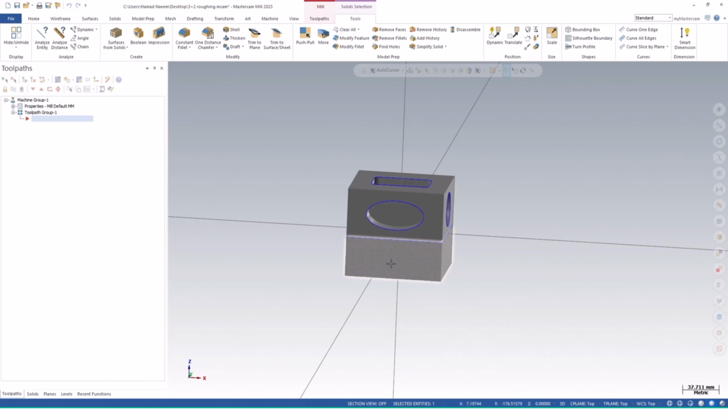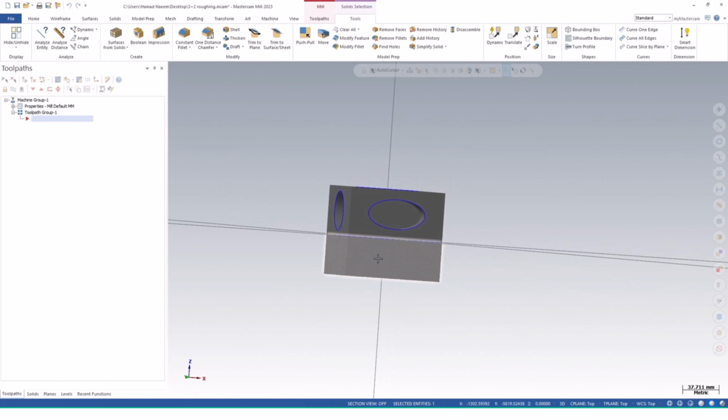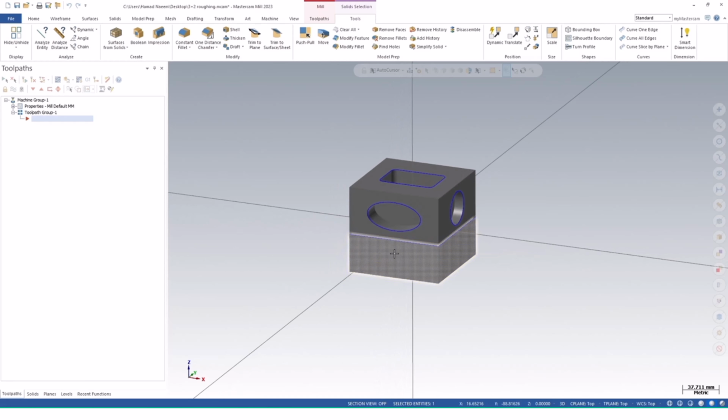On the bottom side, we have a stock fixture setup, which will be held on the chuck of the C-axis. So definitely, the first thing we need to do is 3-axis milling, and then on the other side, we're going to use the other 2 axes. So it's called the 3+2. But the most interesting thing is that it will automatically perform the 3+2 machining operation on this block. So let's see how it's done.